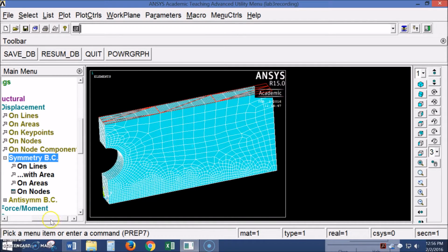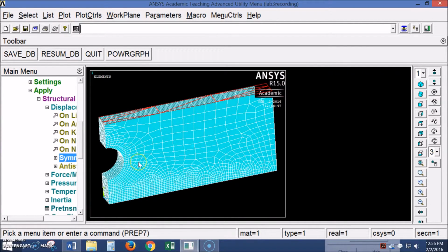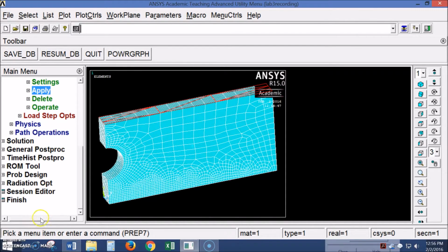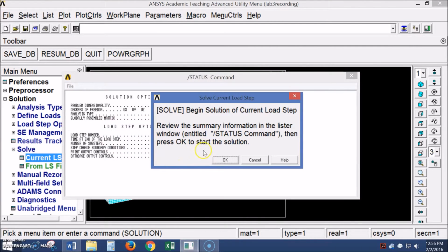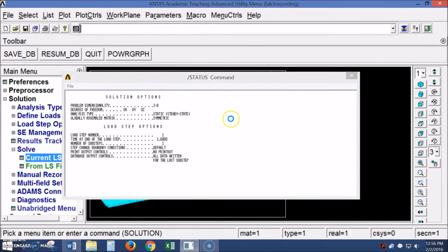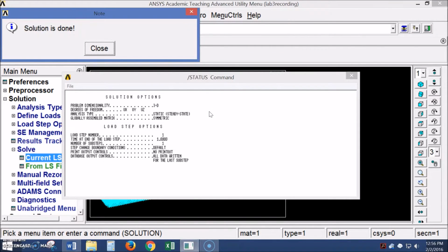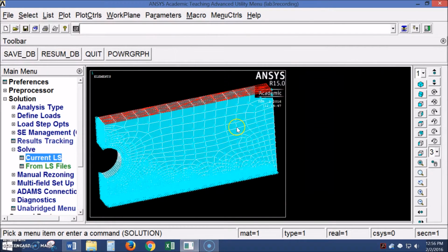So we have a properly constrained plate, because theoretically, we have the X and Y direction constrained with that boundary condition. Because if you have a force on the left and on the right, that net is 0. So we have basically a force and a reaction. And then in Z, I've constrained it as well. So I can now run my solution. As you can see, solid shapes take a lot longer to solve because there's a lot of 3D meshing going on.